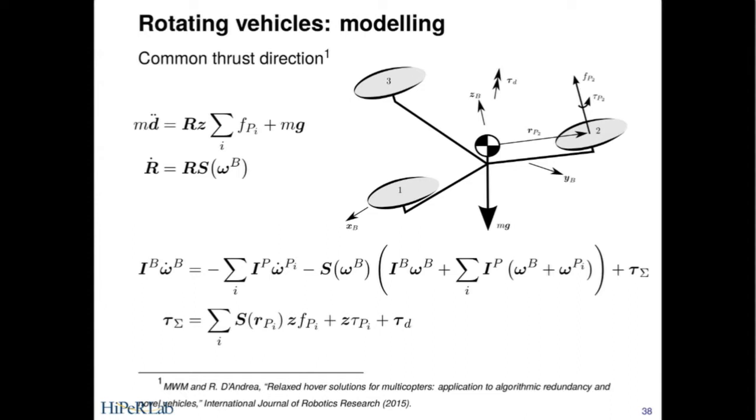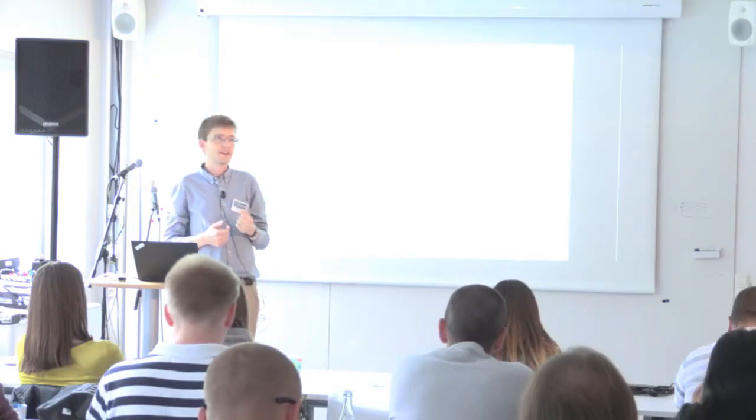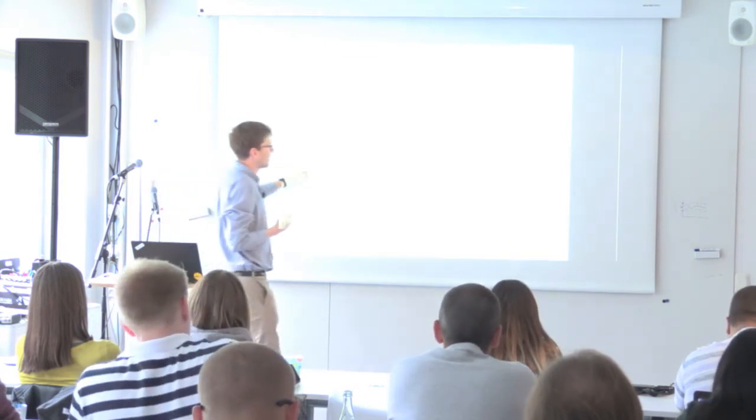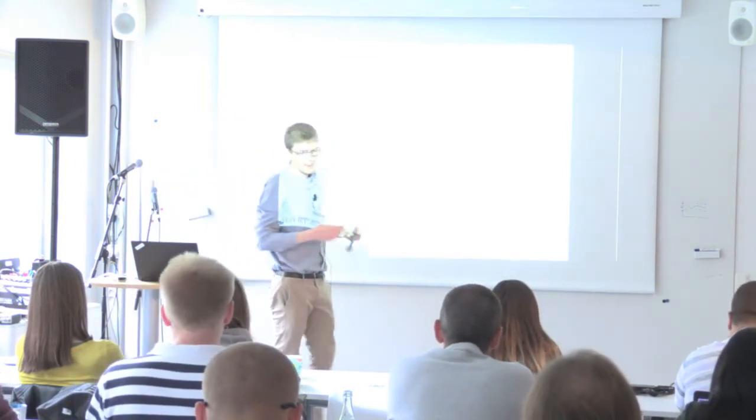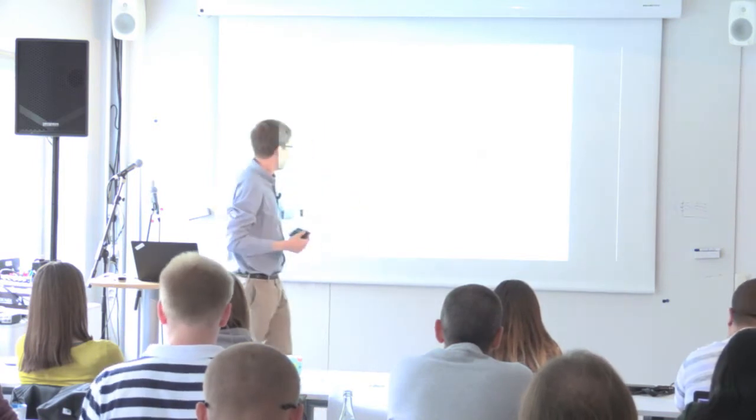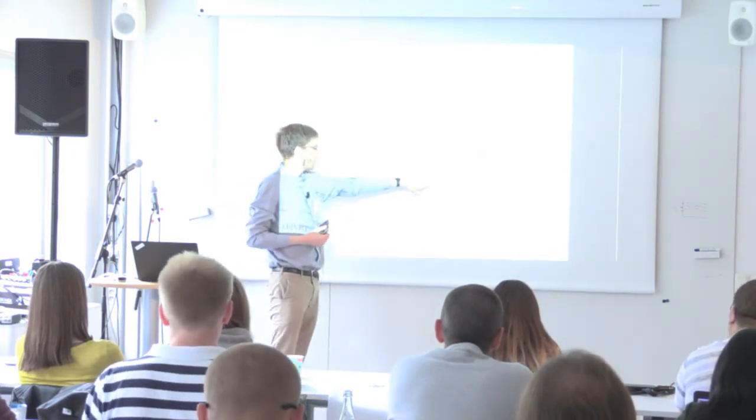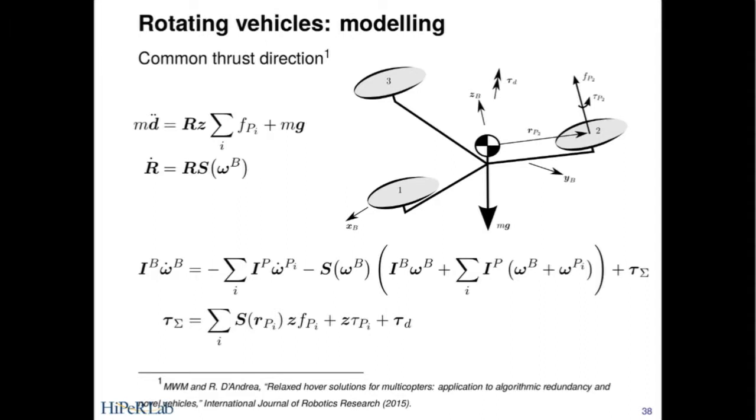It is using these equations that we can realize how to have these vehicles operate when you lose one of the propellers. The key to understanding how this works is to exploit this cross-coupling term, this nonlinear term in the attitude dynamics. Deriving it is relatively complicated, and since there are relatively few mechanical engineers, I suspect most people have not seen how to get to this kind of equation. I'm not going to go into it because it's not that exciting, but I want to give you an example of where you will see this in action.